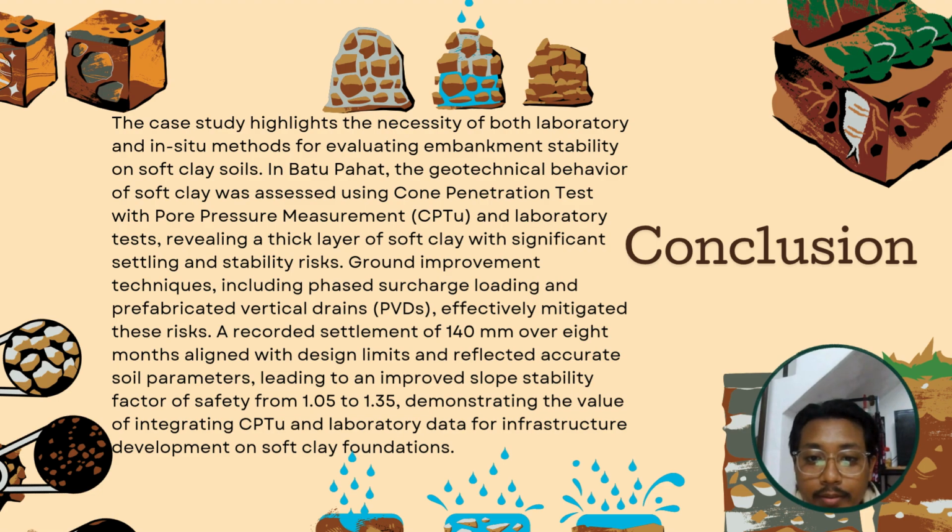A recorded settlement of 140 mm over 8 months aligned with design limits and reflected accurate soil parameters, leading to an improved stability factor of safety from 1.05 to 1.35, demonstrating the value of integrating CPTU and laboratory data for infrastructure development on soft clay foundation.